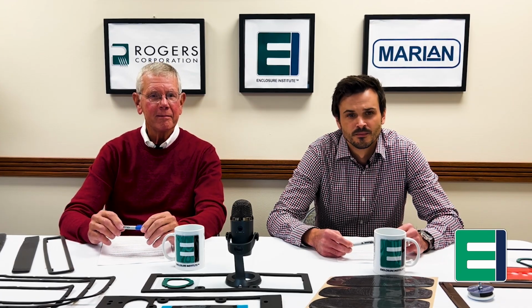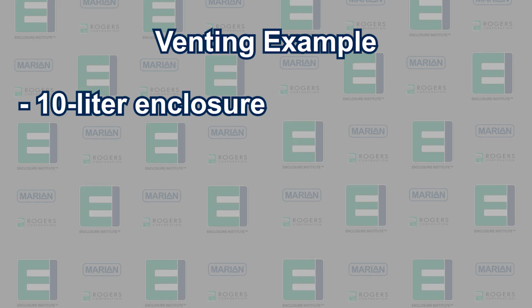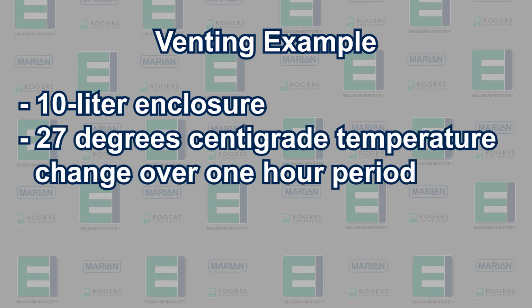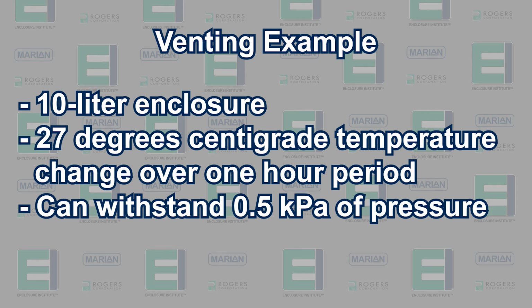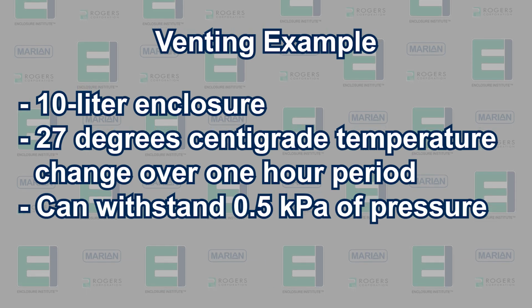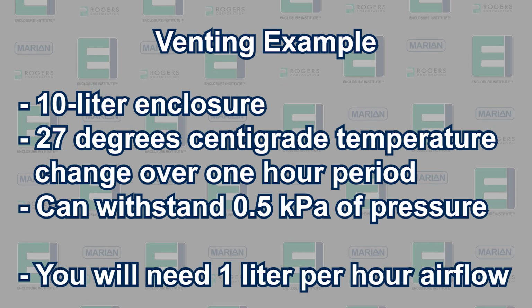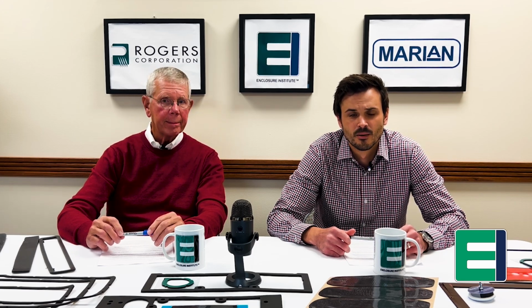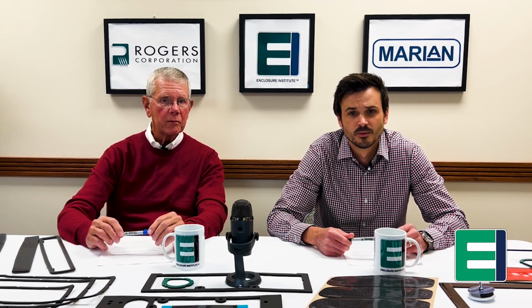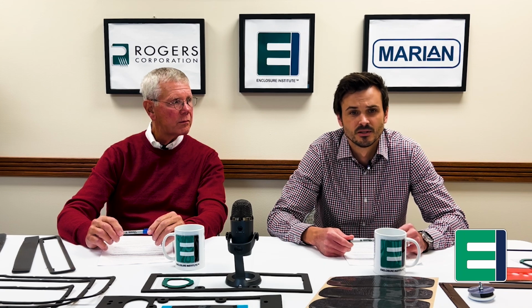Here's an example. If you have a 10-liter enclosure that will normally see a 27 degrees centigrade change over the period of an hour, and your enclosure can withstand 0.5 kilopascals of pressure, then you'll need 1 liter per hour of airflow. Knowing that will allow us to recommend the venting material that gives you the best combination of airflow and water entry pressure resistance within the recommended temperature limits.